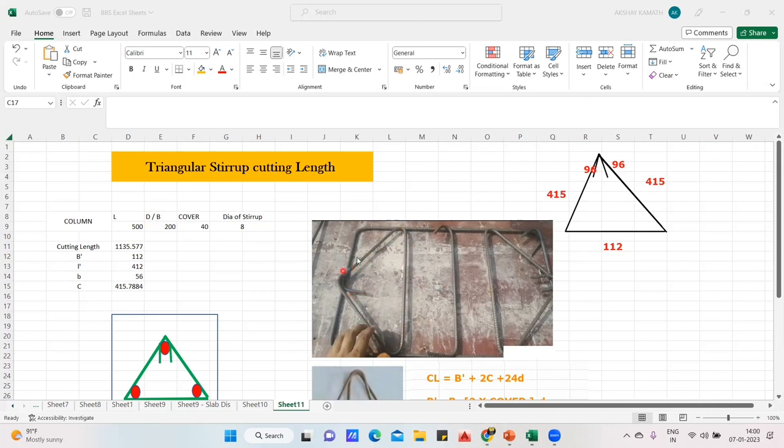The bar bender is going to bend it in this direction. You'll get it. Now again, if you ask me what about the bend deduction, no, bend deduction is not required because the formula is directly taken from the code book. Just in case you don't want to take the formula from the code book, or let us say your company people follow that they have to do the bend deduction, then you do the bend deduction here accordingly. Wherever it has got, the same bend deduction you can do. But bend deduction is not required here.